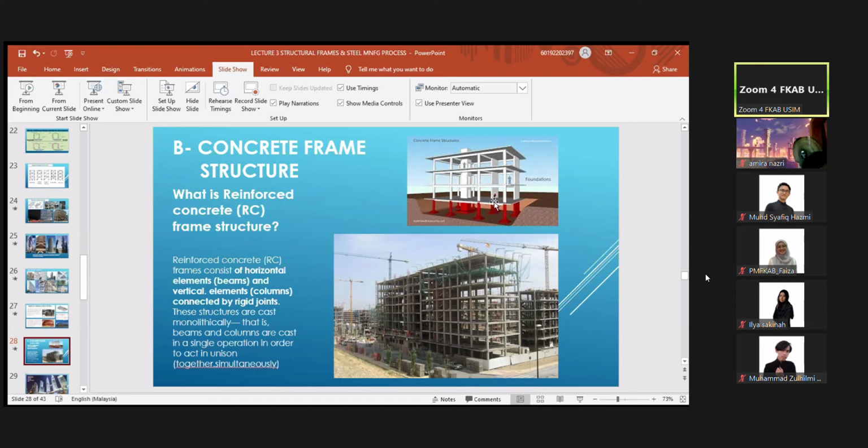The termites come in, they will attack first your timber door frame. Of course, now most of the frames are made of steel, so the termites have a tough time. But they can still come in, and they go up to your roof. First they attack whatever is on the floor. If you have some boxes, their most favorite material is paper boxes, and then they go to your books, your shelf, and then up to your roof trusses. This is how the truss can collapse, because of this cold joint effect. Okay, this is how it's been constructed.